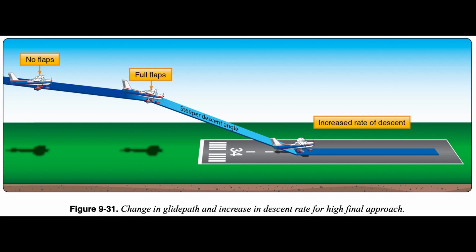Slow final approach. On the final approach, when the airplane is flown at a slower than normal airspeed, the pilot's judgment of the rate of sink, descent, and the height of round out is difficult. During an excessively slow approach, the wing is operating near the critical AOA and, depending on the pitch attitude changes in control usage, the airplane may stall or sink rapidly, contacting the ground with a hard impact. Whenever a slow speed approach is noted, the pilot should apply power to accelerate the airplane and increase the lift to reduce the sink rate and to prevent a stall. This is done while still at a high enough altitude to re-establish the correct approach airspeed and attitude. If too slow and too low, it is best to execute a go-around.